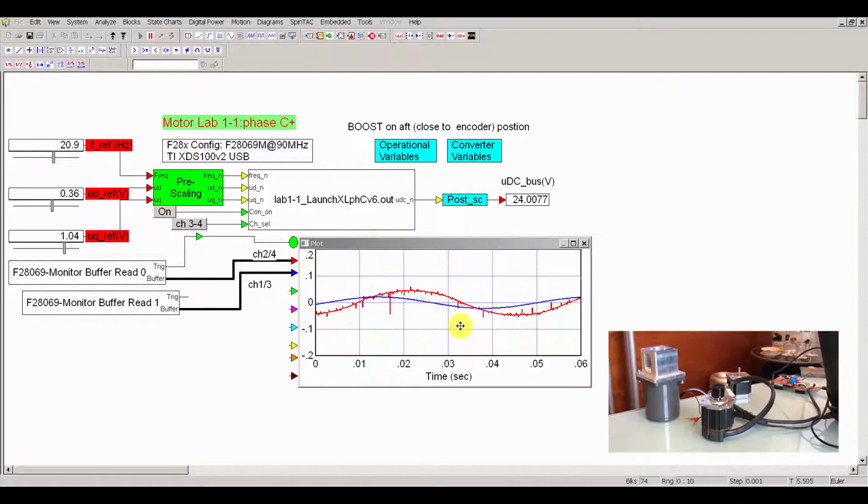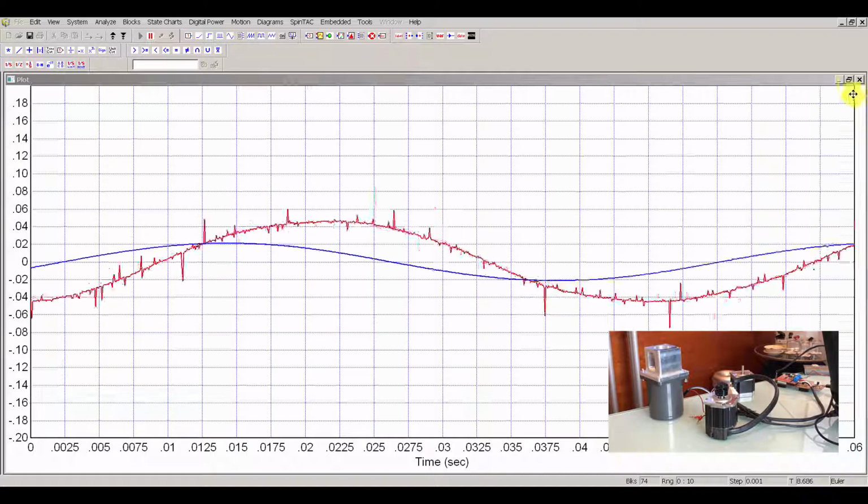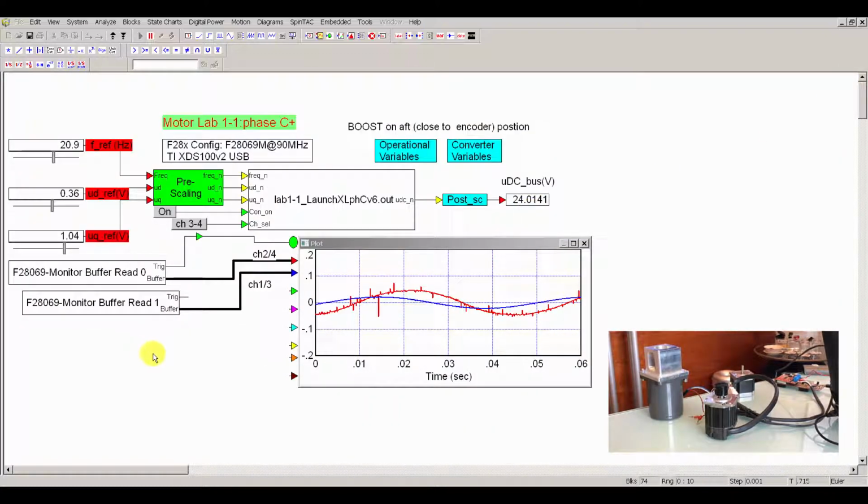And that's the power of VisSim. That is what you can do with no other package: look at actual instantaneous signals. There is noise on the sampled currents. No problem, you can see it and observe it. So that's the first open loop voltage control example of your machine. Once you see these waveforms, you basically have a working setup from which to progress into more advanced structures. This is the first step. The next step will be to do current control.